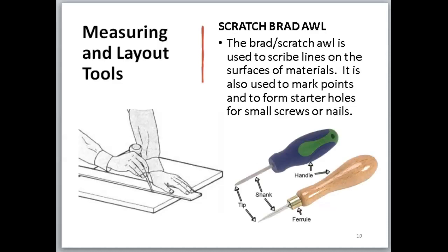Let's look at another measuring and layout tool known as a scratch or brad awl. The brad or scratch awl is used to scribe lines on the surfaces of materials. It is also used to mark points and to form starter holes for small screws or nails.